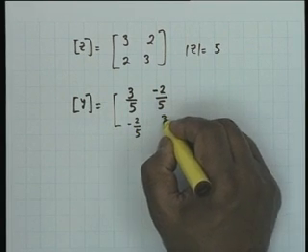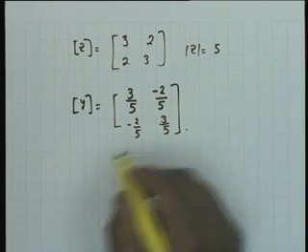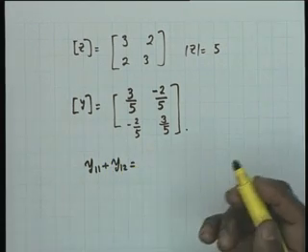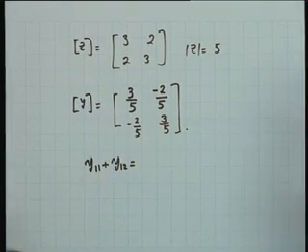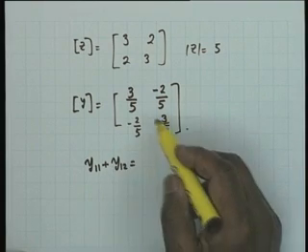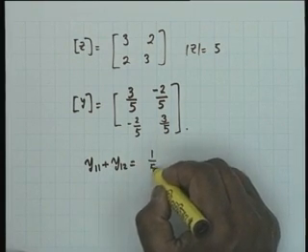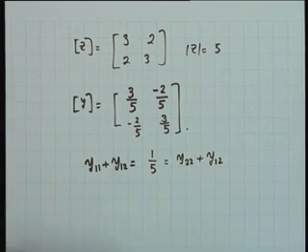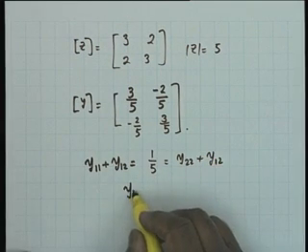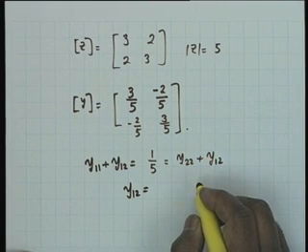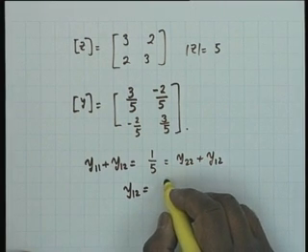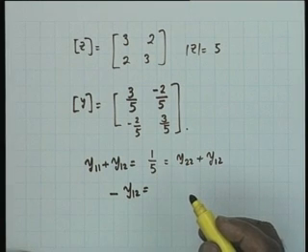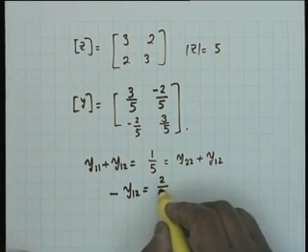Therefore, Y11 plus Y12, we need this for the equivalent pi network, Y11 plus Y12, 1 by 5, this is equal to Y22 plus Y12, and Y12 is equal to, pardon me, minus 2 by 5. What I need is minus Y12, so it is 2 by 5. Instead of doing this directly, we can add the Y parameters of the second.